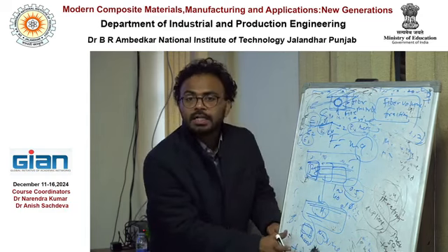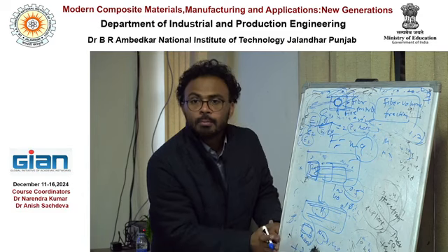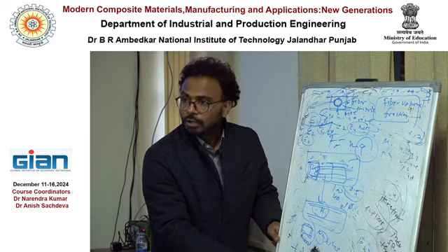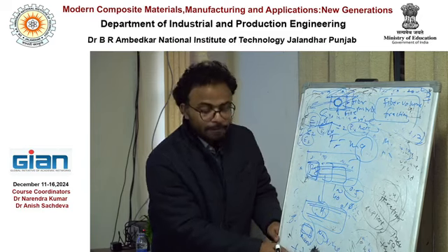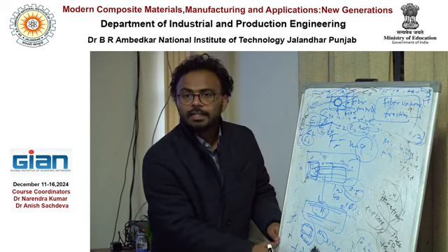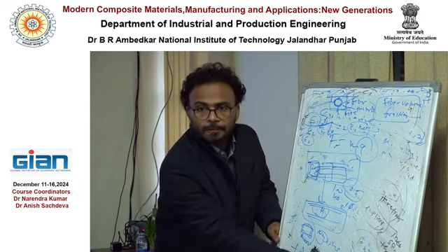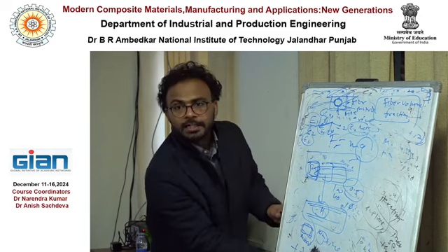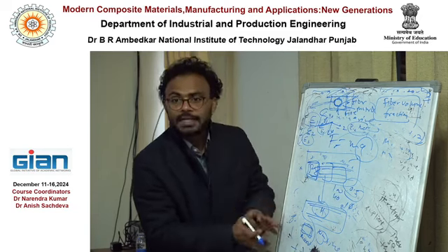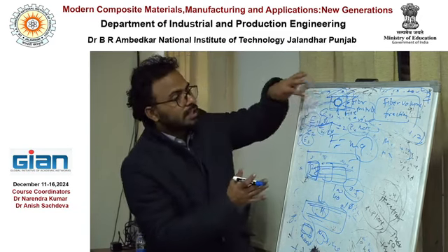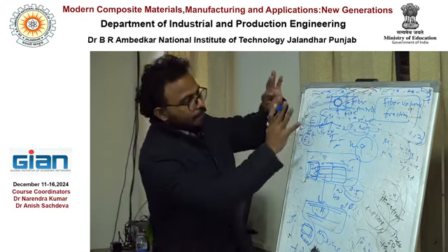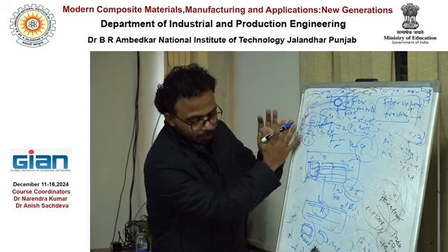Here you do not need to make the composite model. Here you need to make the homogenized model, not isotropic, anisotropic model, the engineering constant model, but no ply needed. Here no ply needed, no fiber needed, no matrix needed. Just a normal model, mesh it, apply those properties here. Now this result will give you the consideration of your matrix and fiber. But when you create this, remember the fiber volume fraction, okay? Getting my point?